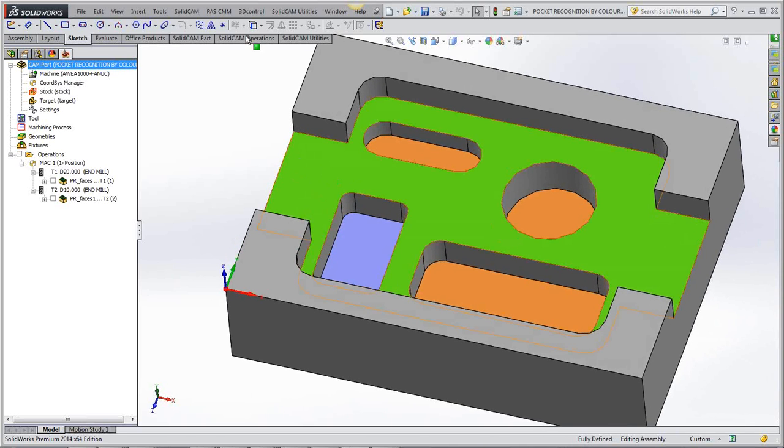where I can come in from the outside, and I've got a big radius here on these corners of 10 millimeters. I say big, 10 millimeters, and I can fit a largish tool, a maximum of 20 millimeters tool in there to do that and finish that quite nicely. We've got a part in here where our radius is only 9 point something millimeters, so we know our 20 milli cutter isn't going to fit in there, so we've chosen a different colour for this because we can't have it with our 20 milli cutter.